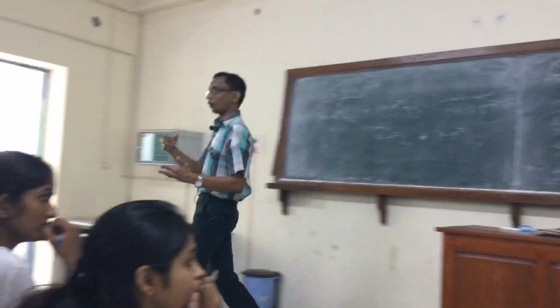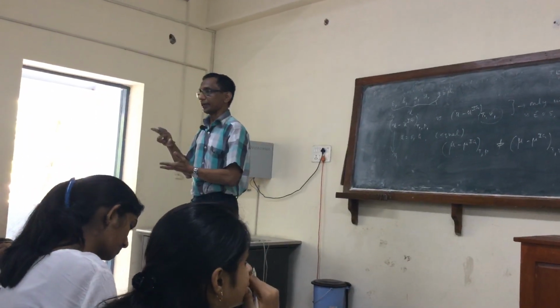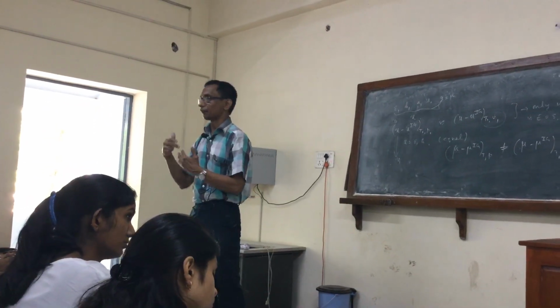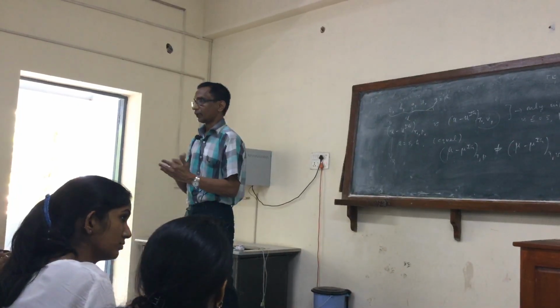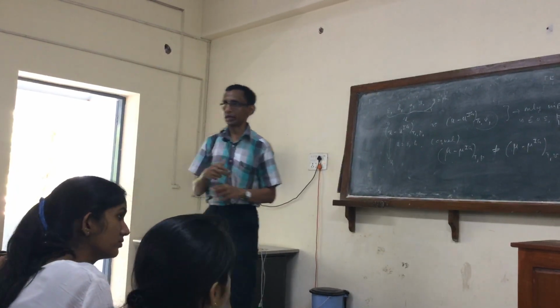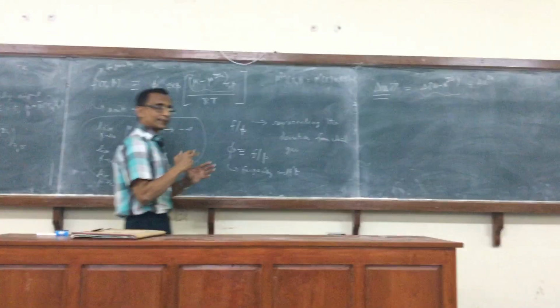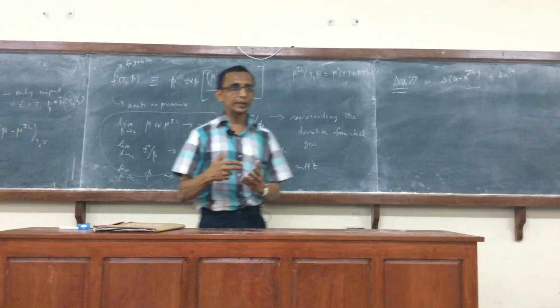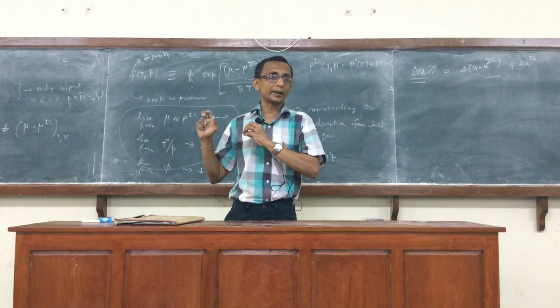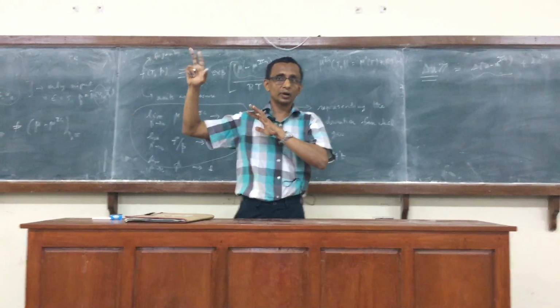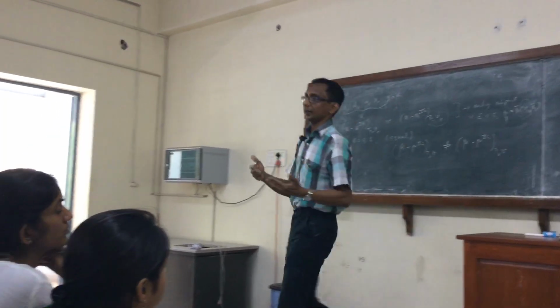So this is indirectly adopting the path C that we took, calculating the difference in property between any two states by going through the ideal gas state. So we separate it, and it's easier to look at it in two parts. And if you look at the formula for delta U that we got for path C, we will have both the specific heat and the equation of state part.